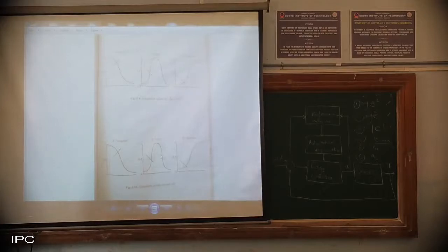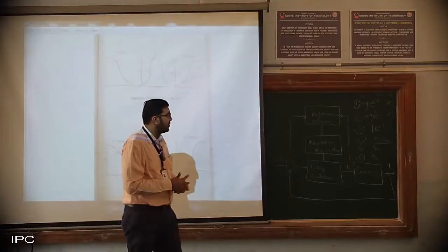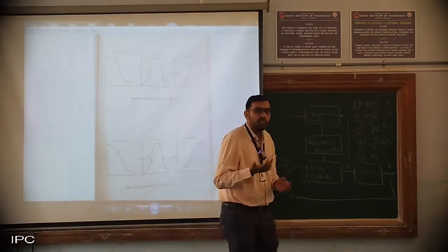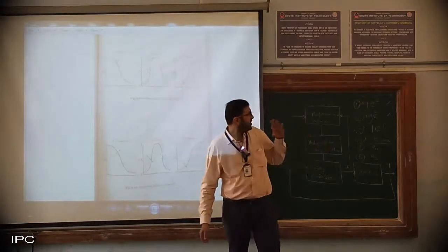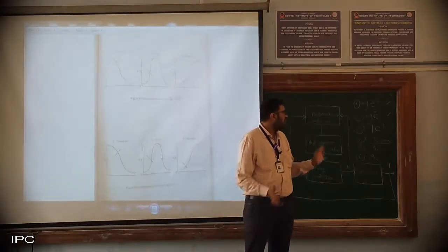So this is how we are going to work on membership function tuning using the performance criteria. What we can understand from this concept is that it depends upon the performance of the system. What are the parameters we are considering for the performance of the system? They are average error, average square of the error, absolute error, and maximum error.